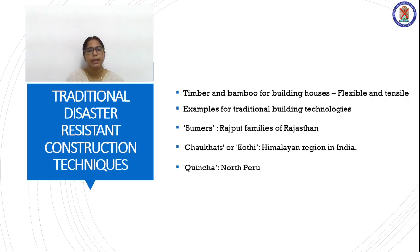Older houses at high elevations have timber roofs held together by timber tie bands. Horizontal timber beams span across the entire building, connecting the entire structure and giving it the character of a cage. So such houses have suffered little damage despite the mud and stone masonry.